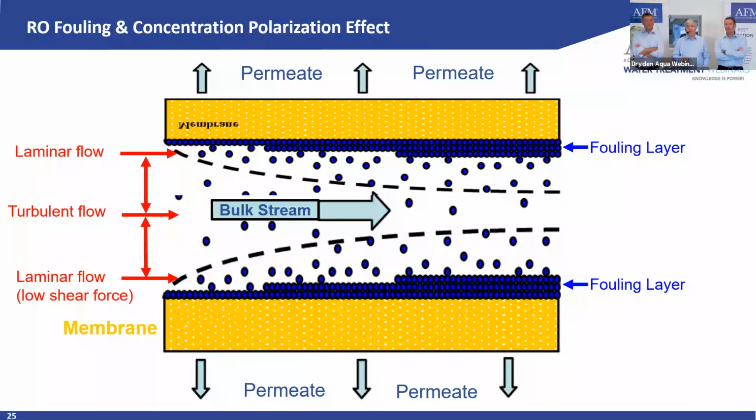So we talk about fouling here. That means everything which comes in will then attach to the membrane surface. It can be any fouling, from biofouling, which is the worst one, actually the most difficult one, but can also be particulate fouling. They will attach to the surface and generate almost like a second layer of membrane. It's not a membrane, but it generates a resistance for the water to flow through. Like a second and third layer. It's a combination of biofouling and particulate fouling.